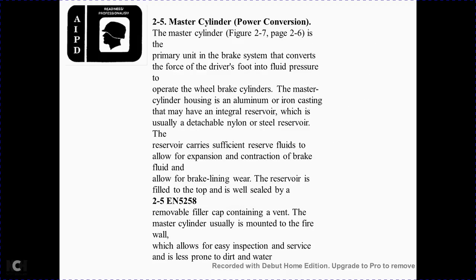2-5 Brake cylinder power conversion. The master cylinder, figure 2-7, is the primary unit of the brake cylinder that converts the force of the driver's foot into fluid pressure in the brake cylinder. The master cylinder housing is an aluminum or iron casting, with an integral reservoir or a detachable nylon or steel reservoir.